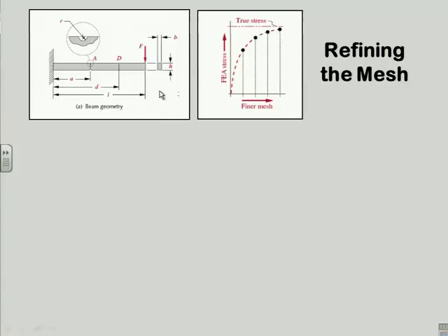Geometry is simple, and so forth and so on. I know the formulas. So I can find out what the classical method tells me the stresses and deflections should be in this thing for a given set of loads. And then I can compare the results from my FEA to the classical solution. And what I will do then is play with the density of the mesh until I get close enough that I don't care about the error anymore, okay?